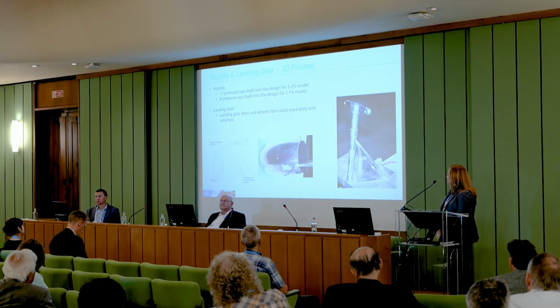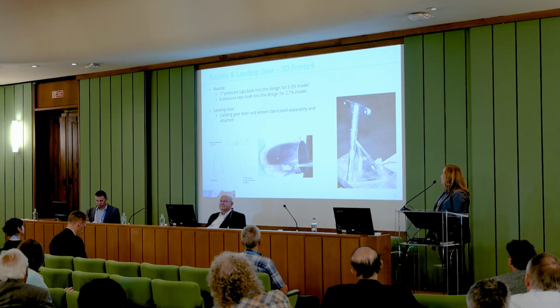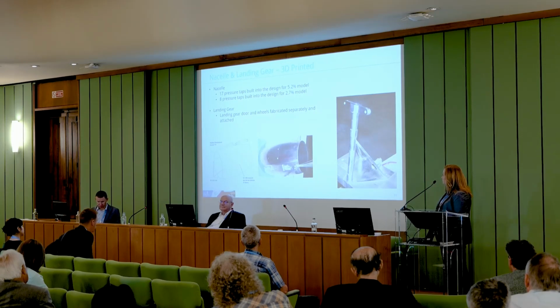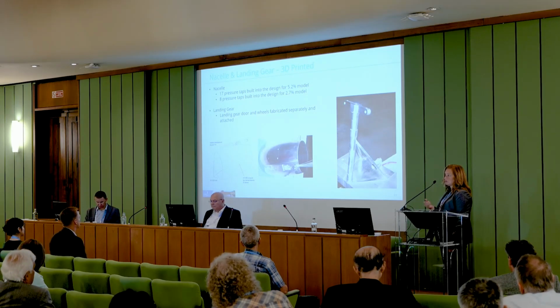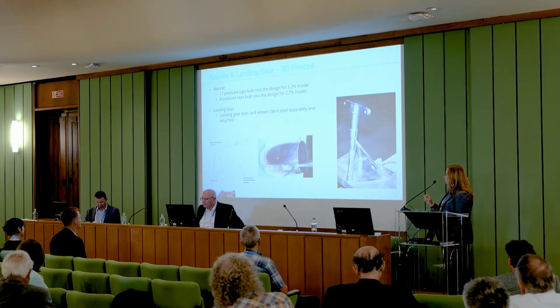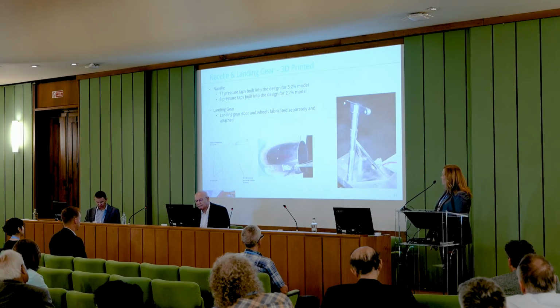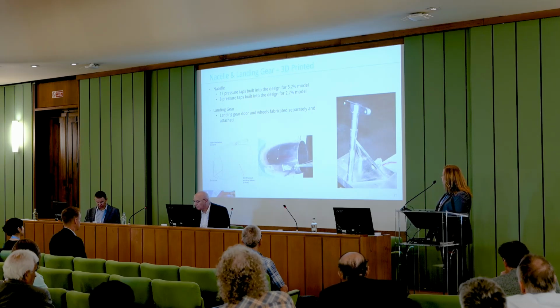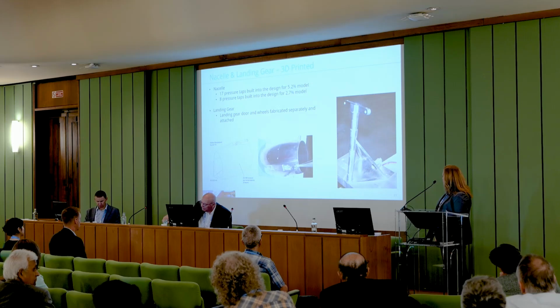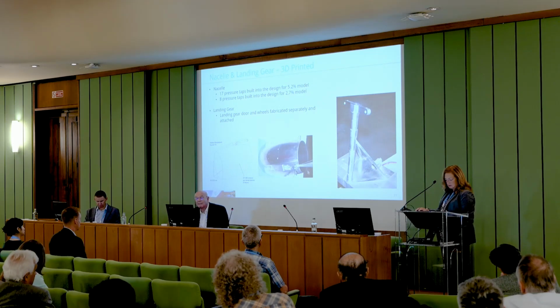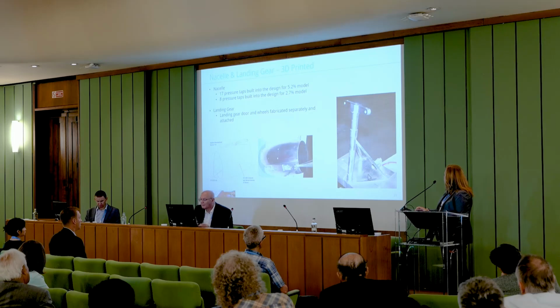Okay, something else different about this model is we were able to 3D print both the nacelle and the landing gear. For the nacelle, what we were really excited about was we were able to build the pressure taps into the nacelle itself. So there was no routing, nothing needed whenever it was fabricated. And for the 2.7%, we were able to have 8 pressure taps built into that nacelle. For the landing gear door, that you see right here, and the landing gear itself were fabricated separately and then attached.